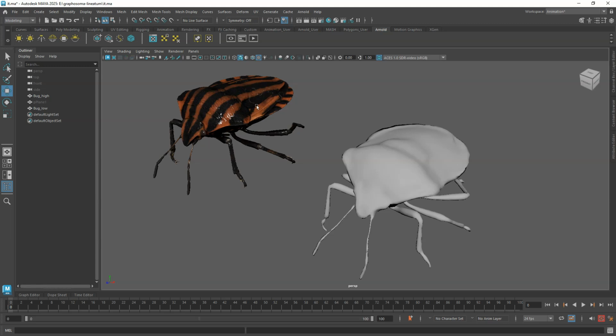And we want to be able to use this same bitmap, this texture map that's on here, on this one. Now this one right now, once we retopologized it, since the material's bitmap is snapped to the vertices, and we have a different set of vertices on this, then this no longer has a viable UV map on it.